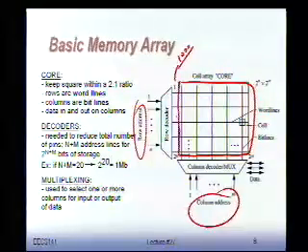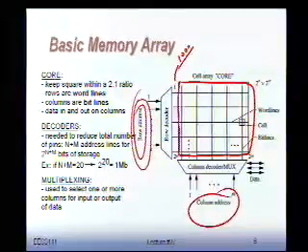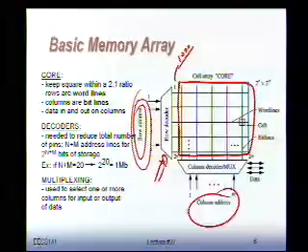So rather than presenting the address in pure one-hot format, we really use an encoded format. Well, actually, we use a binary representation. Because 1000 lines can be addressed by log base 2 of 1000, that's 10 bits. With 10 bits, binary encoded, I can select any one out of 1000. So the first block you will see when the address comes into memory is what's called a row decoder. Something that takes your 10 bits in and turns it into 1000 lines, and out of these 1000, only a single one will be high at any point in time. Because obviously you want to only address one row at a time.